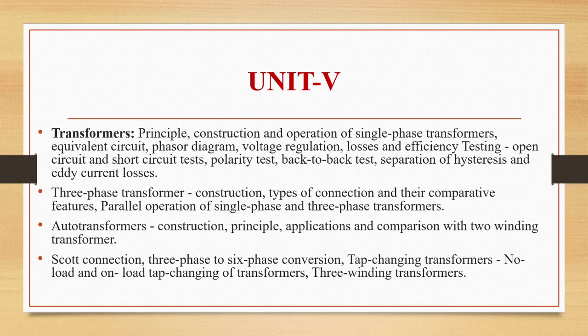There are no rotating parts in a transformer. So there are no mechanical losses or rotating losses in the transformer. There are only iron and copper losses. Because losses are less, efficiency will be more in case of a transformer. Even if you do the experiments, if you have seen in the laboratory, in the OC and SC tests also, we have seen that the efficiency of the transformer will be more.